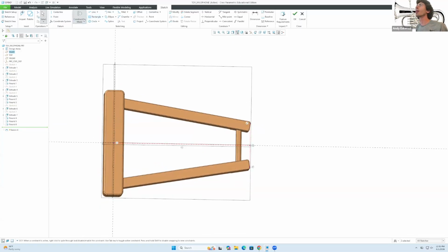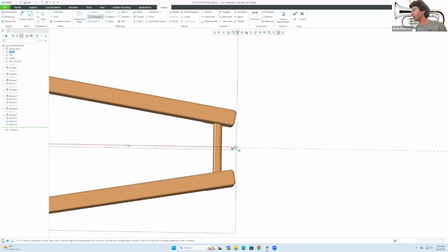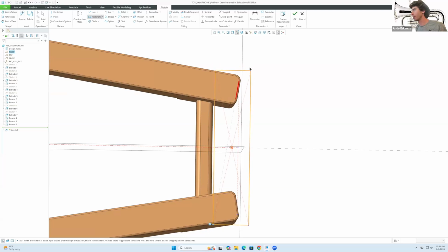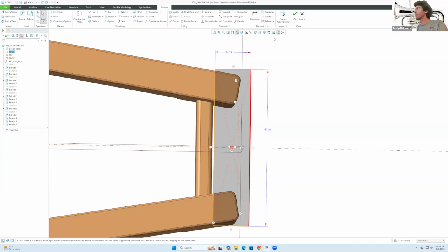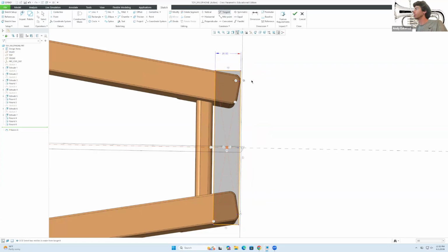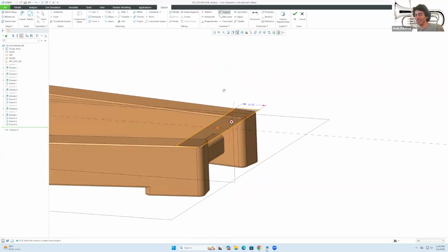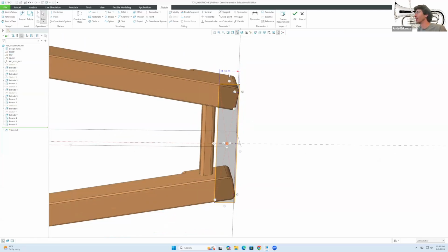And now I want to finish that mode and I'm going to build a center rectangle. Yeah, somewhere, doesn't matter. Good. And what I can say is I want this line, if I go here to tangent, I want that line and that edge to be tangent. So this is how I know that it's exactly on the edge, which is what we kind of wanted. So at least that's defined on that orientation. And we can make that block be 40, but we don't want, let me see.